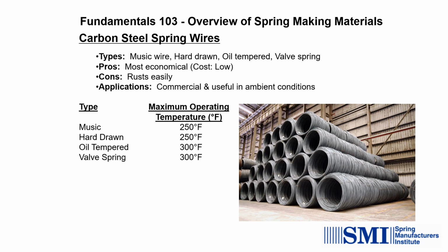Carbon steel spring wires. Types: music wire, hard drawn, oil tempered, and valve spring. Pros: they're the most economical. Cons: they rust rather easily. The applications are commercial and useful in ambient conditions.